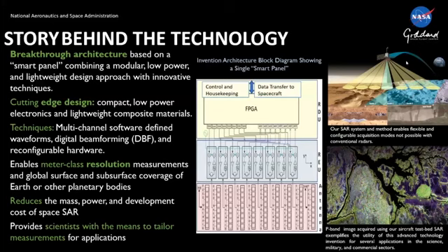It has multi-channel software-defined waveforms, digital beamforming, and reconfigurable hardware, all on the same panel. The antenna and the electronics for beamforming are on the panel, and they are reconfigurable on the fly.